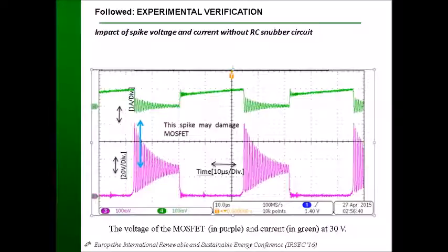But imagine yourself using 300 volt, how much voltage spike you will get on the MOSFET. This high voltage will definitely damage the MOSFET. The voltage rating for a MOSFET is around 100 to 1200 volt, but if you make it 100, there will be more spike and ringing on the MOSFET.